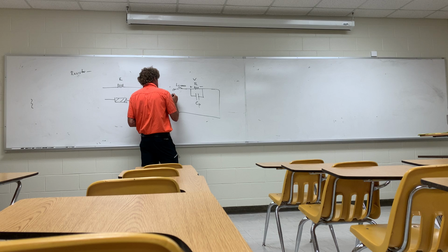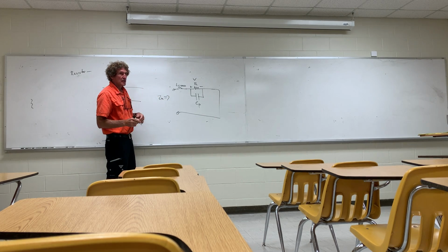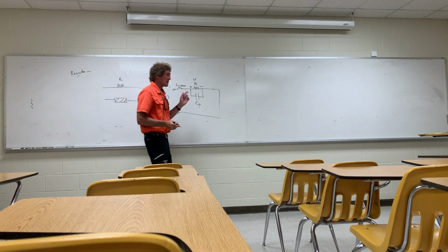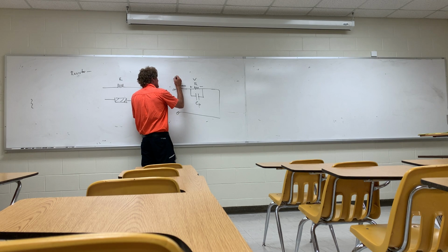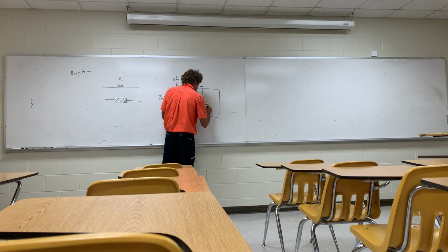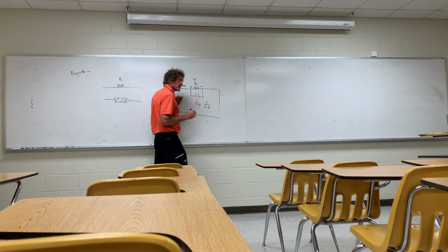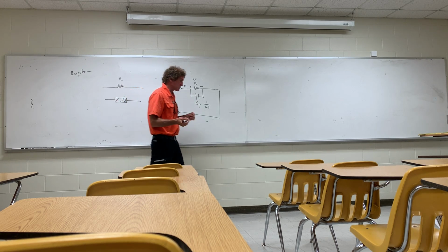So if you wanted to take a look at Z input for this, the input impedance of this right here, and we can do this in the S domain, well, the impedance of the inductor is what? It's just SL, right? The impedance of the capacitor right here is 1 over CS, right? Do y'all follow me? S is really what? Sigma plus j omega. You have the Laplace transform, right? But we normally do it with S with analysis.